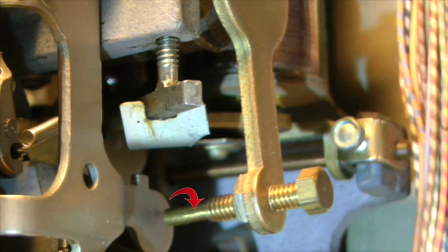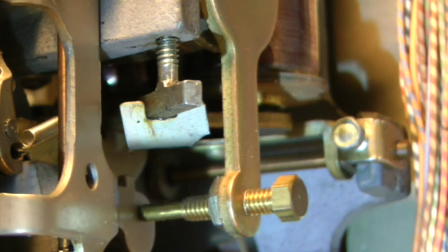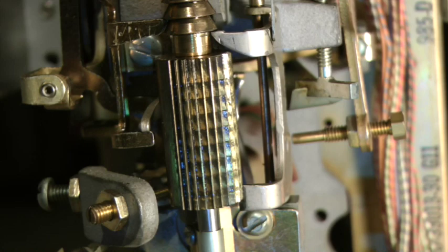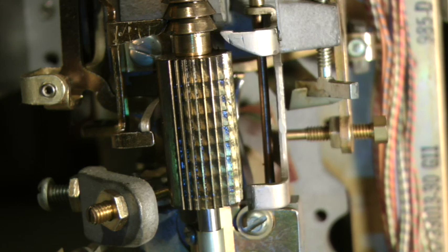Attached to the bottom of the armature is a pin. Each time the release armature is attracted to its coil, the pin engages the head of the double dog. This causes the double dog to pivot, disengaging its legs from the vertical and rotary ratchets. This permits the shaft to rotate anti-clockwise to its rotary normal position.